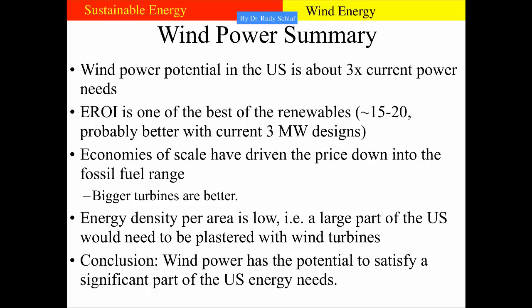Summarizing, we can say the wind power potential in the US is about 3 times the current power needs. The EROI of wind power is probably the best of all the renewable technologies. It's about 15 to 20, probably better with current 3 megawatt designs. The price of wind turbines is now in the fossil fuel range. This comes mainly from installing ever bigger turbines.